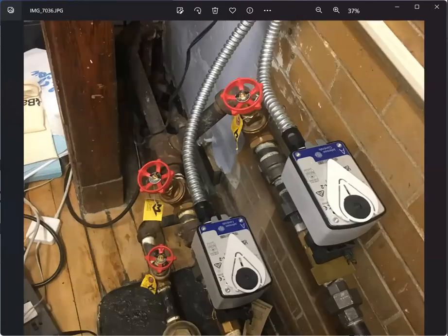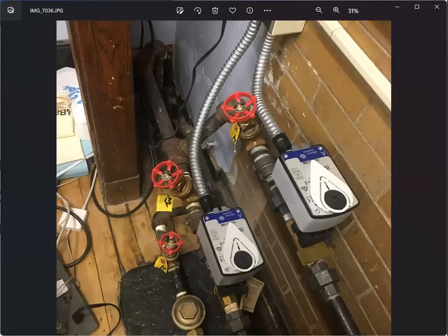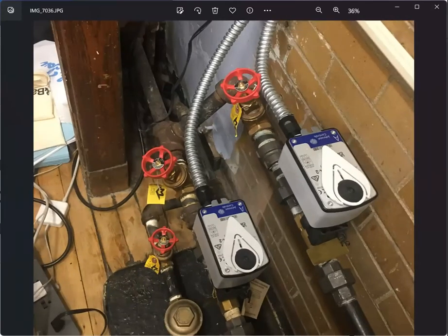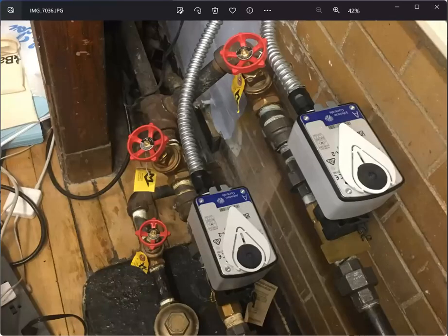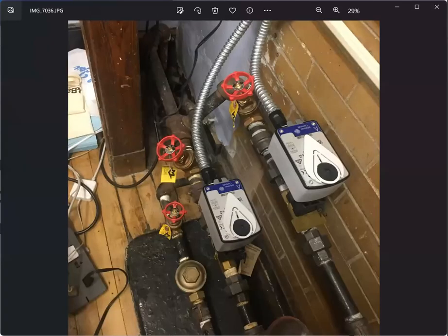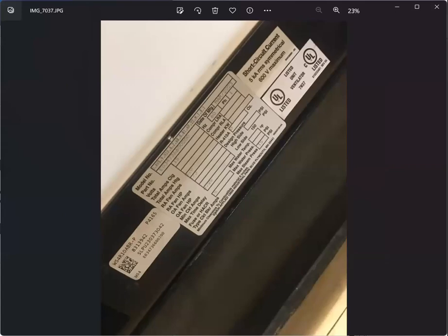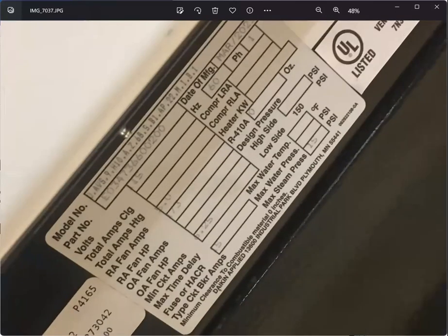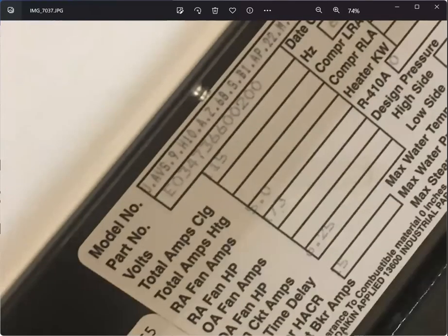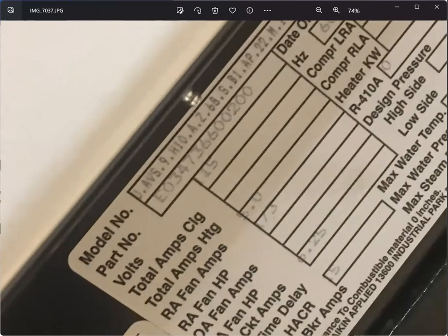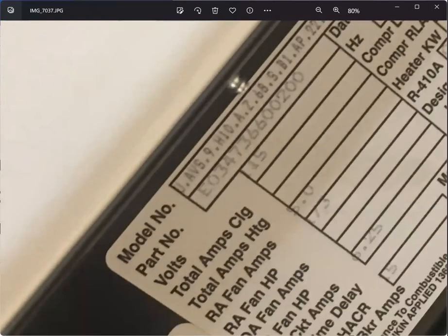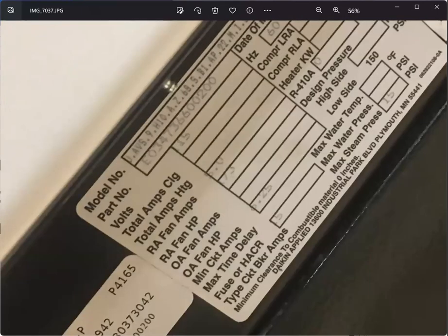In this case, you got two control valves because you got two lines of supply piping, and one condensate return right here. Another name tag, so take note. I will show you the specs, the approved submittals for each one of these capacities. This is H10. This represents like 1,000 CFM.